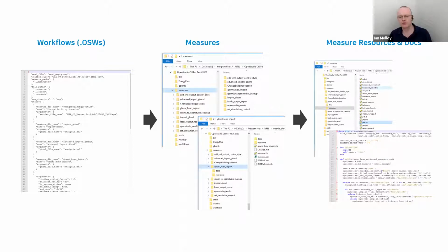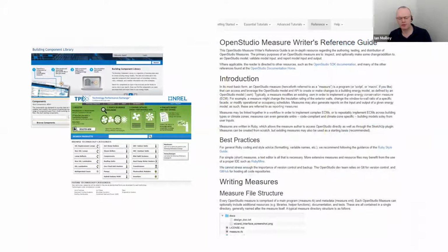So you can dig all the way through and see, for example, here are all the properties of all the HVAC equipment. So for example, here's the simplest one. Here's a PTAC. So you can see its COP and things like that are all set in here. Its cooling design temperature and heating design temperature and so on. So you could get another manufacturer's equipment there, change it, and simulate the effect of that.